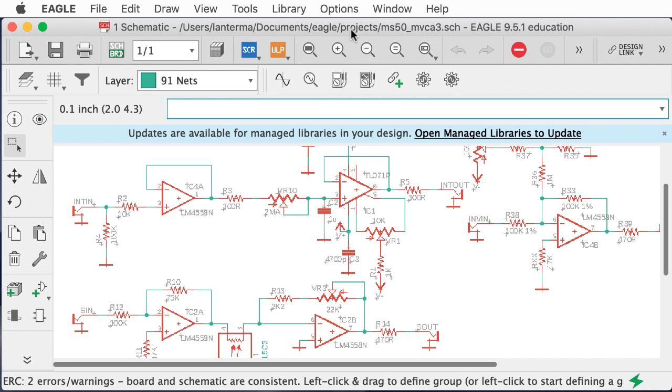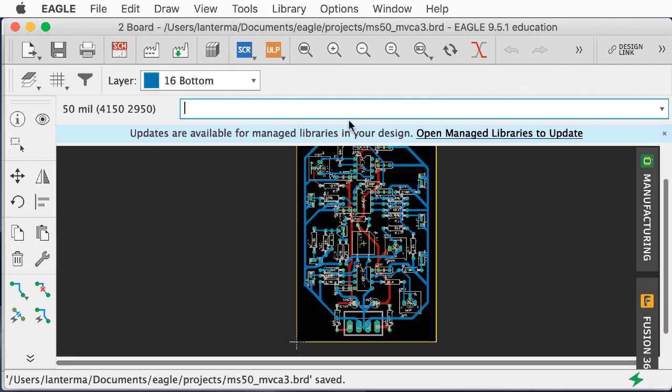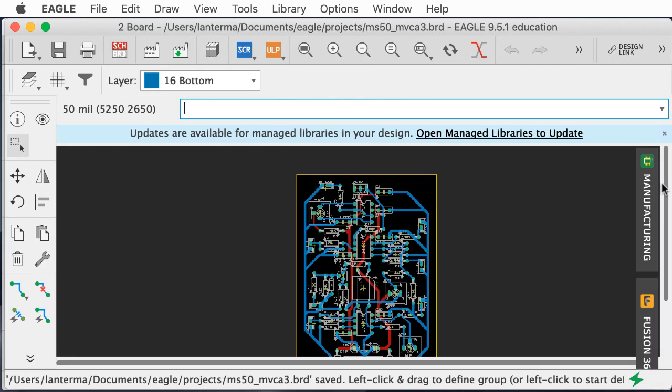One thing as a side, it's very important once you create this board that you always have the board file and the schematic file up at the same time so things stay in sync. Now there is a useful command, I haven't needed to use it here, called replace. It also works on the schematic. So say it turns out that you said make the board and you have a whole bunch of resistors over here that you're expecting to be through hole. And instead it turns out, oh no, they're surface mount devices.